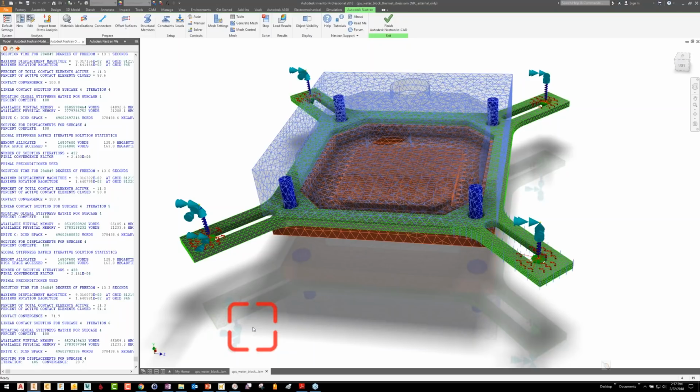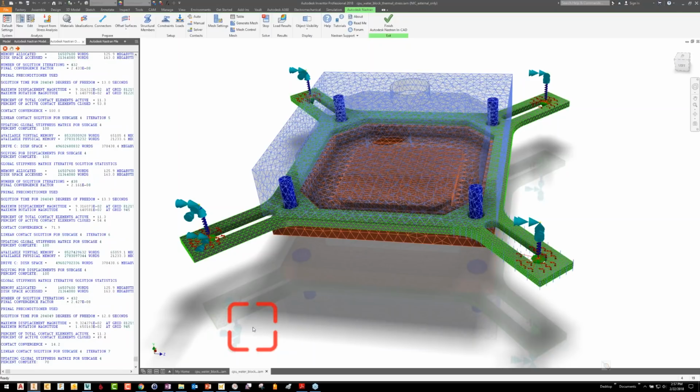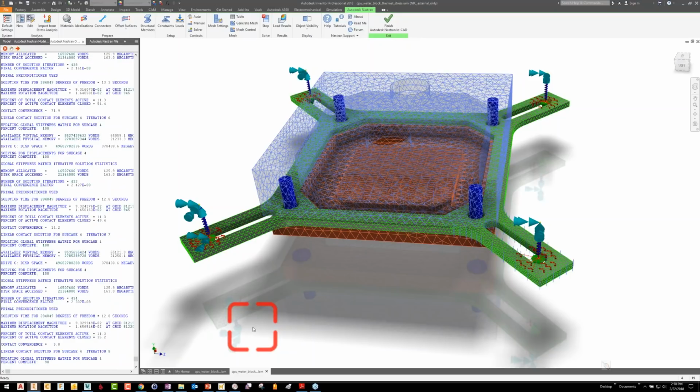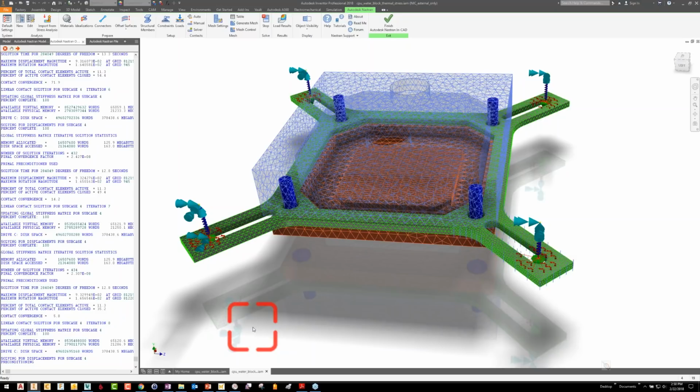I guess maybe I can explain what I meant earlier about how you technically go nonlinear when you add a surface contact. If you think about what's going on with the separation contact, I keep calling it surface, but it's separation. If parts are separating, then the area that's in contact is changing, right? So really the force is getting transferred between the two, or the location of those forces is changing.